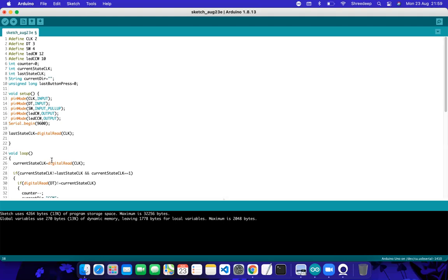What I'm trying to make you understand is that the blink function that you have written in the last program has to be called from either the setup function or the loop function, because in Arduino there are only two software void functions available. One is setup, one is loop. So all the functions existing in your program must be called from either of the two functions.